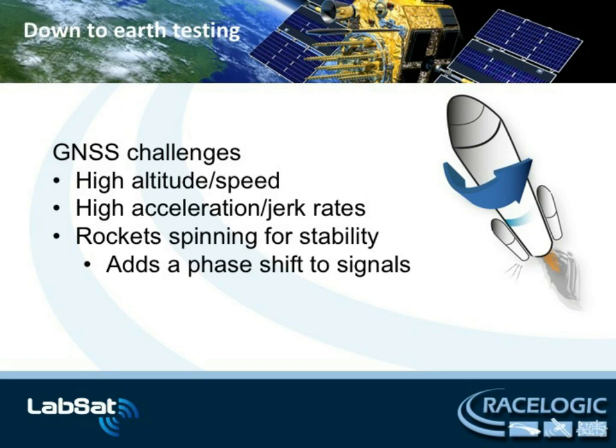From this, they will be able to record a real rotating antenna signal and play this back on the bench. This will allow them to repeat the test as many times as they like to see how this affects the performance and measurements of the receiver. The tracking loop of the receiver can then be adjusted whilst observing the output of the receiver to get the best possible results.